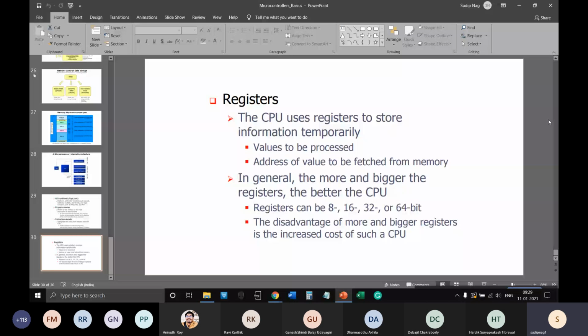Okay, and there is 8086, but I don't cover that because there is no point. It gives you a completely different direction, it takes a lot of time, and it is not used in embedded computers these days. Most importantly, the purpose of embedded systems is not served by 86 series processors in general, because they are very power hungry and have complex instruction sets. Complex means very long, lengthy, and quite difficult, with a lot of things to remember. You have to mug up a lot of things. Rather, we'll only go through 8051 and ARM.